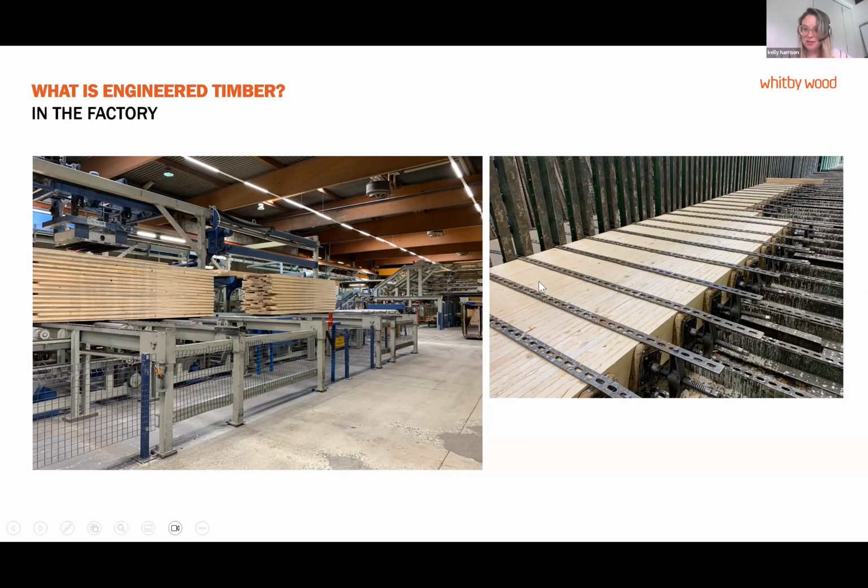Now this was an extremely long curved beam, so they're not normally created in such elaborate pressing, but it was rigged up especially for this sort of long curved beam that was stepped at the ends as well. So you can see at the end, they've stepped the lamellas rather than making a whole piece and then cutting it later. So it's very materially efficient the way they've done this one. So that's being pressed with the glue between.